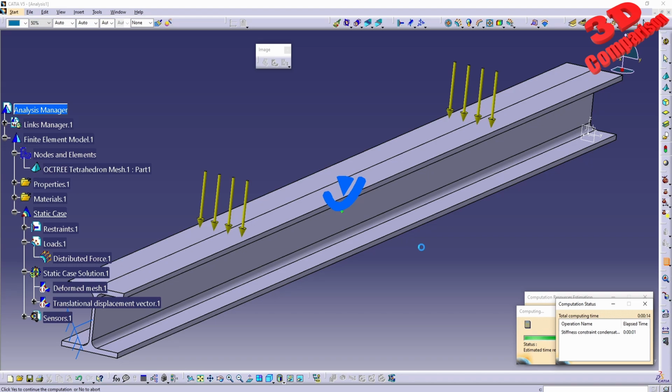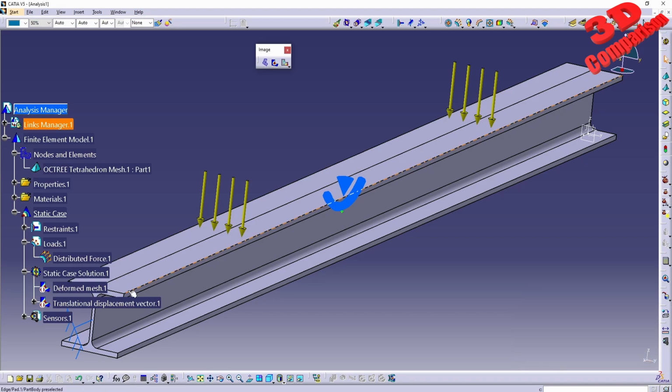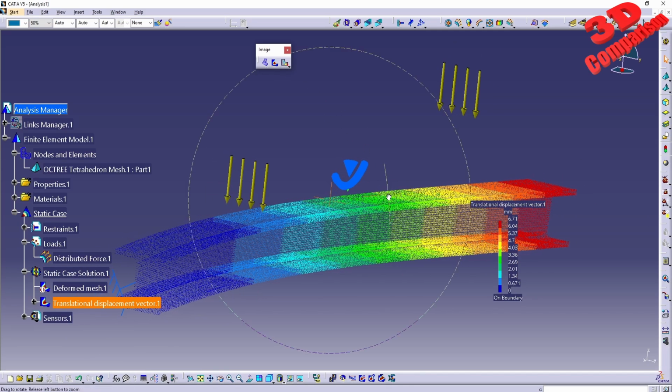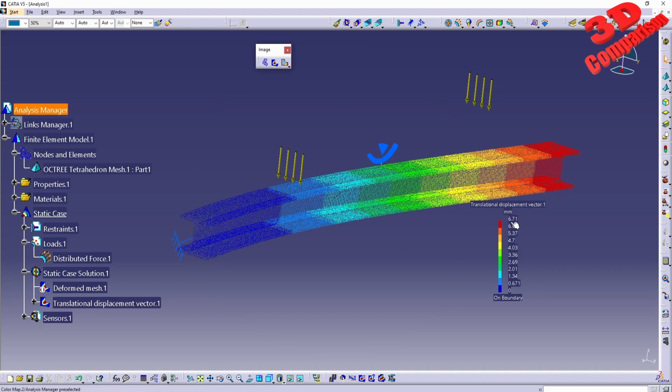So usually if you go for lower values, the mesh will be divided into smaller elements and the calculation will take a lot longer. Just like we see now, I jumped from the 126 it was initially to 20 and now to 4. And now we can again see those displacements over here. In this case, we see the value for the displacement. This went all the way to 6.71. So it didn't go that far from the previous result, even though the mesh now is a lot smoother.